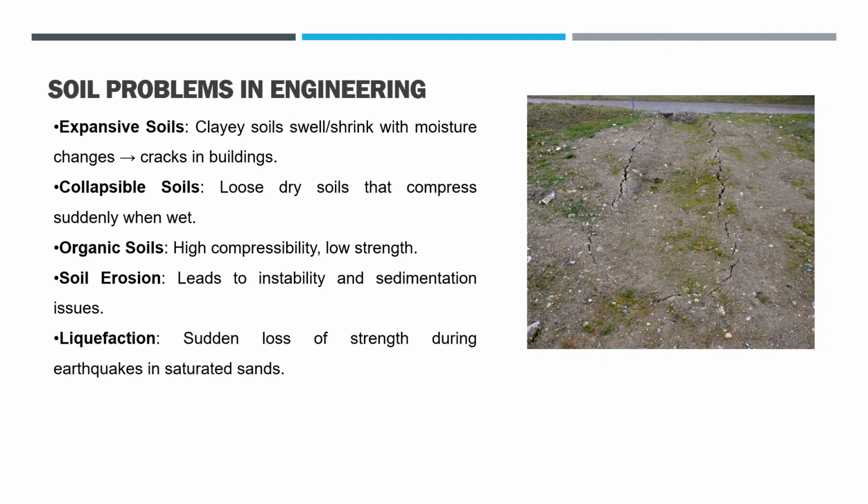And next is organic soil. If the underlying soil is of an organic nature, because of its high compressibility and low strength, the complete structure gets damaged. Next, if the soil is of erosive nature, this may lead to instability and sedimentation issues.